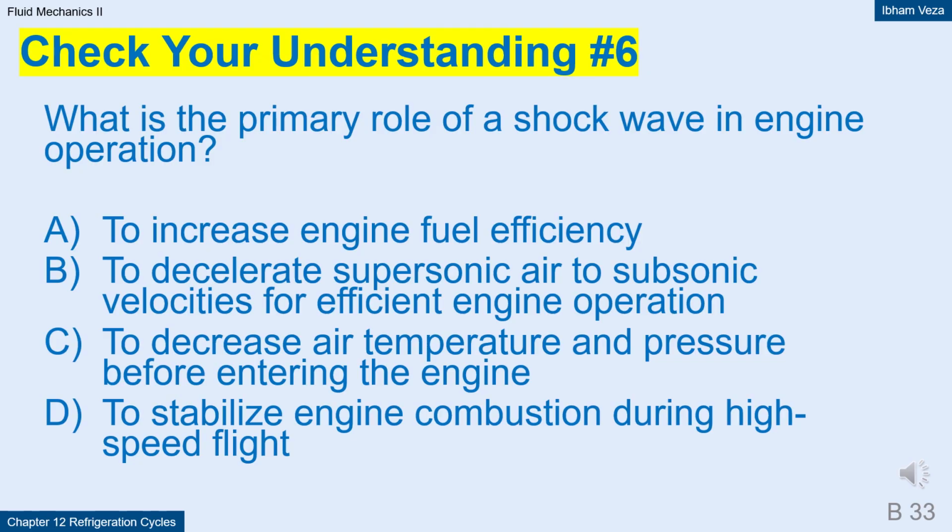B. To decelerate supersonic air to subsonic velocities for efficient engine operation. This is the correct answer because the shock wave's primary function is to slow down supersonic air to subsonic speeds, allowing proper conditions for engine operation.